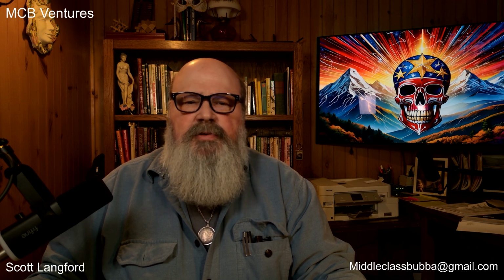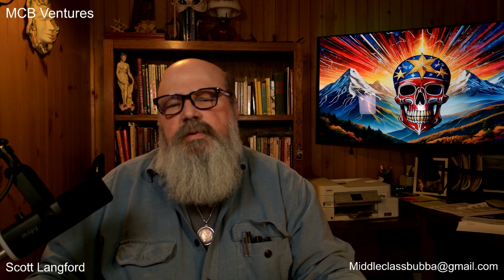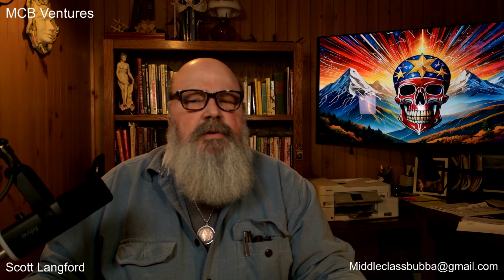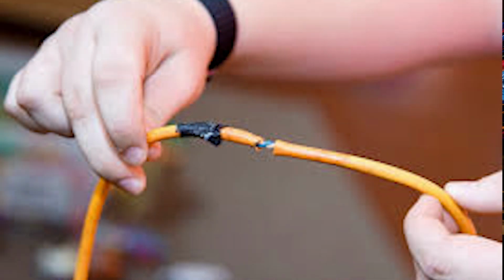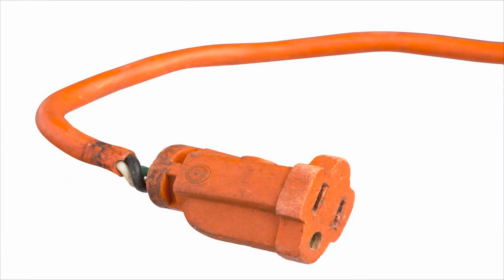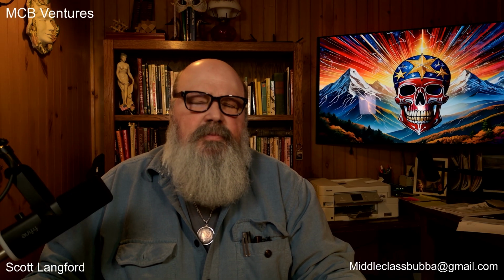Number two, damaged equipment, cords, and faulty wiring. Electrical tools, extension cords, and wiring degrade over time. Look for frayed insulation, exposed wires, or damaged plugs before using equipment. Remove defective tools from service immediately.